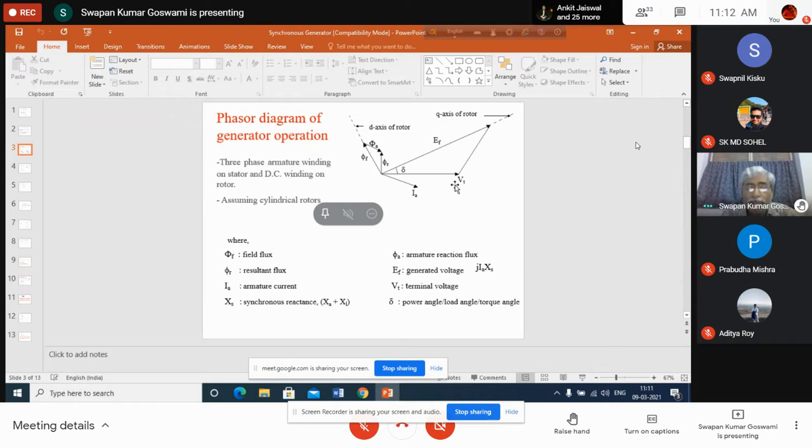You cannot change it, because the power system is maintaining that frequency constant, and your generator is very small compared to the capacity of the total power system. That's why, whatever the power variation of your generator, it has no capability to control the frequency of the infinite bus, because the infinite bus is of infinite capacity. This is our assumption. In practice that will not happen, but we shall be analyzing those things later on. For the time being, we are assuming that the frequency of the infinite bus is constant, so the frequency of Vt is constant.